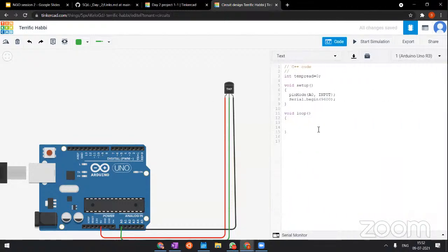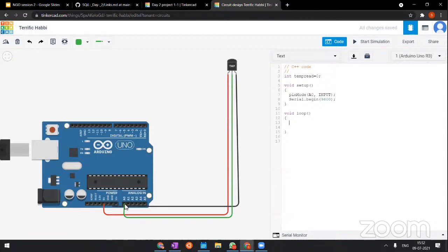All right, so I was going to explain to you about the void loop. The analog pin A0 is going to be used as an input pin here, not an output pin. In the LED program, we used digitalWrite because that is a digital pin and we were outputting a value to it. Over here, it's an input pin. Most of you might have guessed it, it's very intuitive. The function is called analogRead.